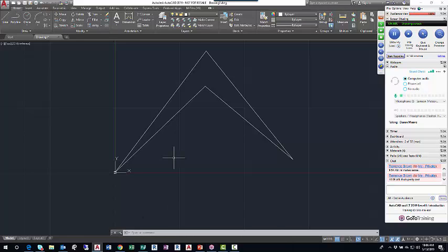So you actually have supplemental information. Maybe you saw that. If I start that same command again, at my crosshairs, at the bottom right corner, this is a dynamic input tooltip. Dynamic input is another tool that's on by default. It's an assist tool that allows you to see the command prompts not just at the bottom of the screen, but at your crosshairs, where you're more likely to be looking anyways. If there's anything exciting happening in AutoCAD, it's going to be right at your crosshairs.